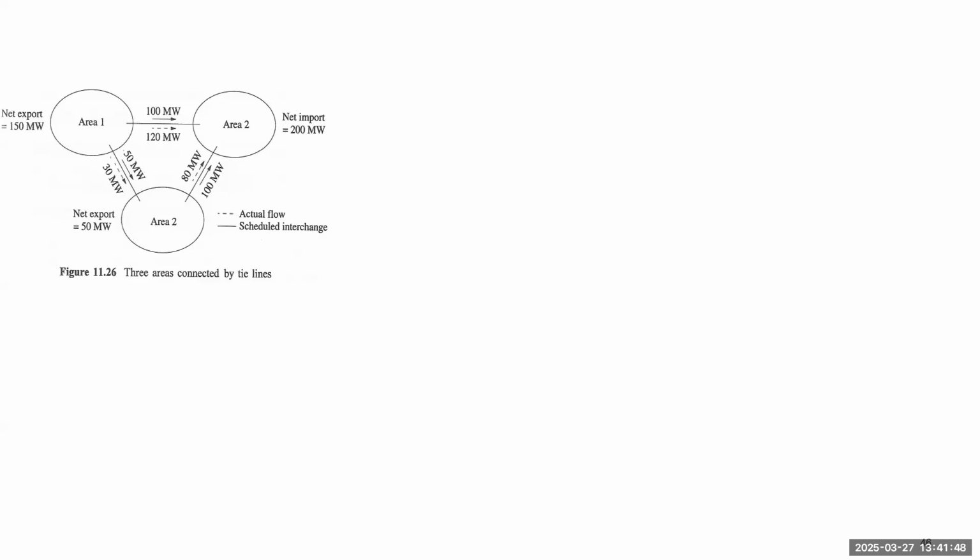For example, for area 1, you can schedule both tie lines and include both tie line flow and frequency deviation in the ACE, or you can also include just some of the tie lines. You can customize ACE based on what you expect for the system.